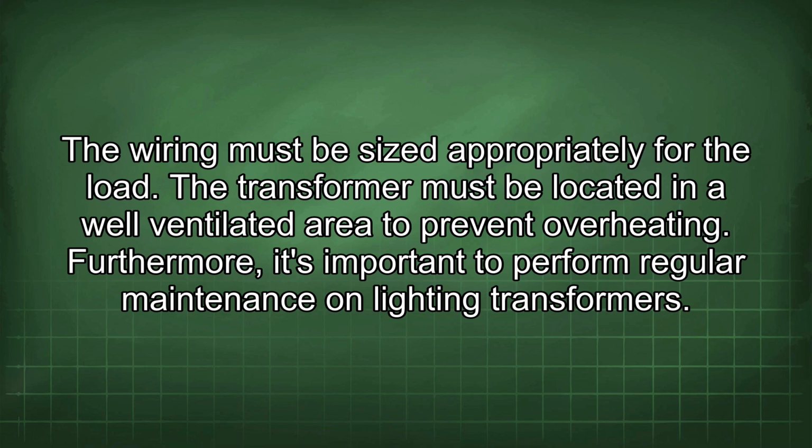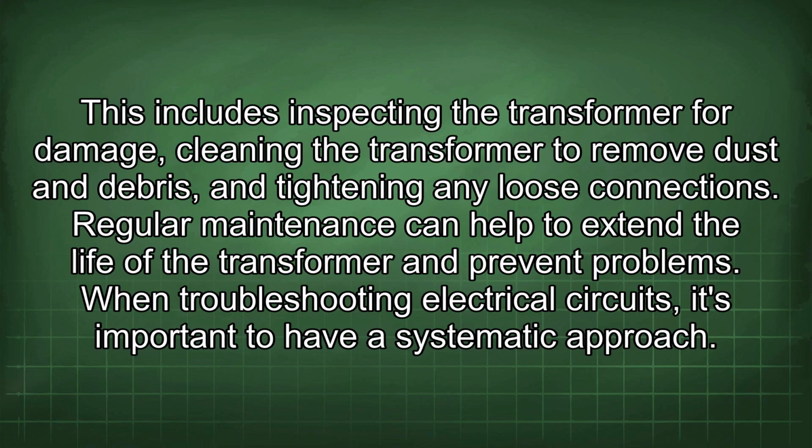Furthermore, it's important to perform regular maintenance on lighting transformers. This includes inspecting the transformer for damage, cleaning the transformer to remove dust and debris, and tightening any loose connections. Regular maintenance can help to extend the life of the transformer and prevent problems.